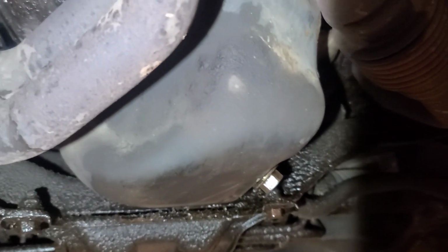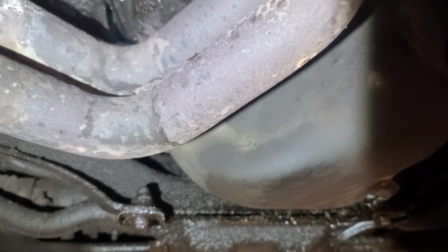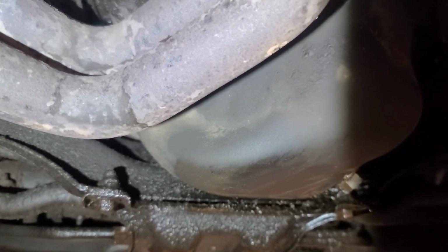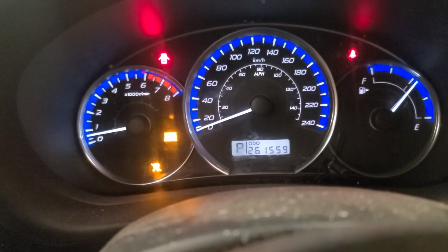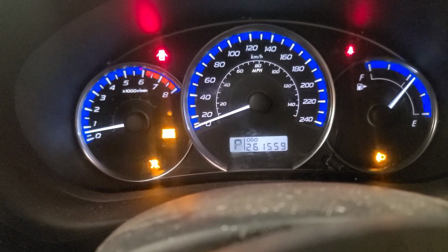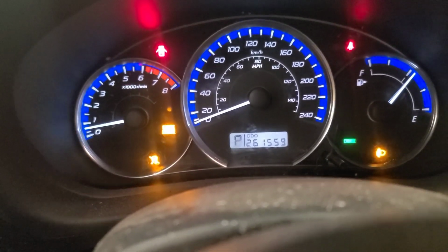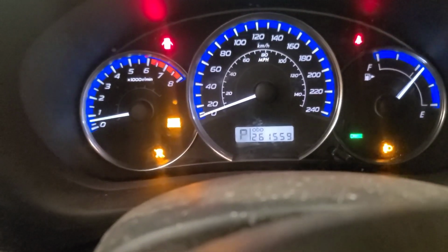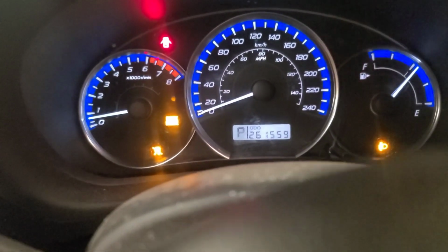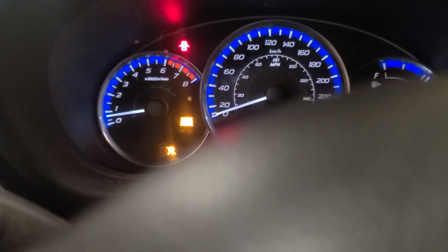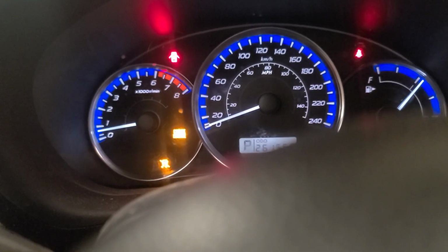And I'm not sure if being in that test mode affects startability or not. It seemed to start okay. It had been sitting for 5 days outside in -20 weather. But we're going to park it outside and let's see how it runs, or starts, tomorrow. So with the check engine light on and the cruise light blinking, the cruise control is not going to work. That's a Subaru function. Whenever there's a significant engine emission related code, they kill the cruise control and the traction control, and likely the ABS too, but it doesn't specify that.